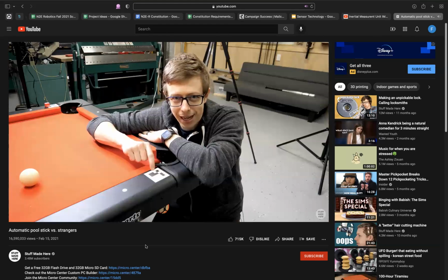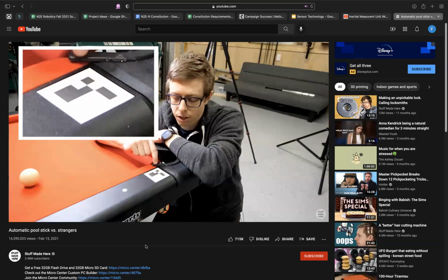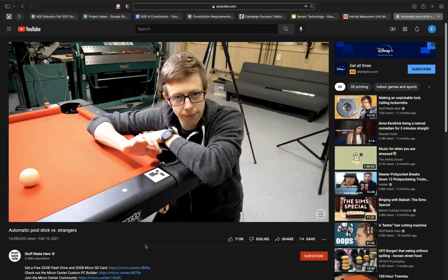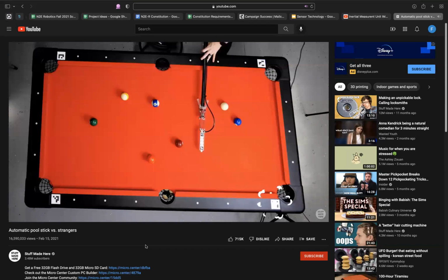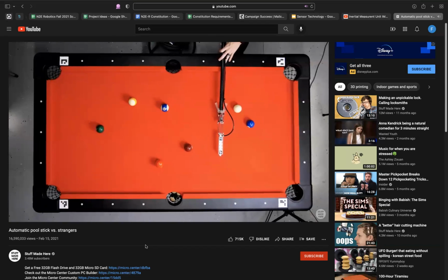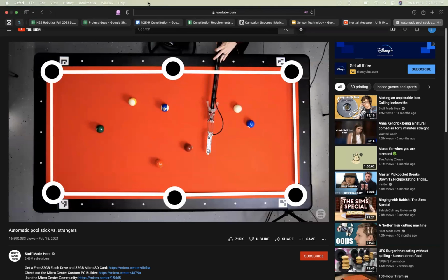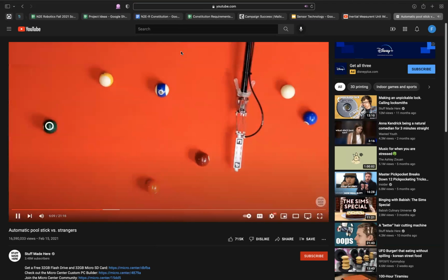I glued these funny looking tags to all the corners of the table, and they're called fiducials. They're basically a reference point that's very easy for a computer to pick out of an image, kind of like a QR code. I can find these 4 points and then use them to straighten the image up. I know where the holes and bumpers are relative to the fiducials, so I know where they are now too. And then if I find...